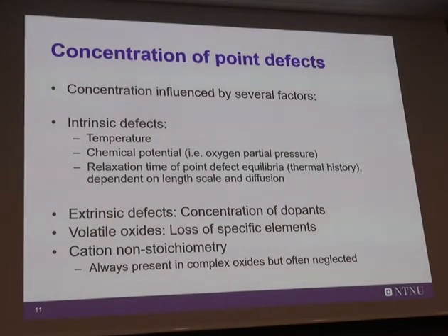So if you make your own barium titanate, it's most likely that you're not able to reproduce what people have done before, because you're not able to have the same precursors with the same chemistry, with the same impurity level and so on, in order to control that the barium to titanium ratio is actually 1:1. And that's a really important thing with respect to the functional properties. Unfortunately, it's not very often focused on in the literature, because it's difficult and you don't know. And things you don't know, you don't write. So this is a very important thing.